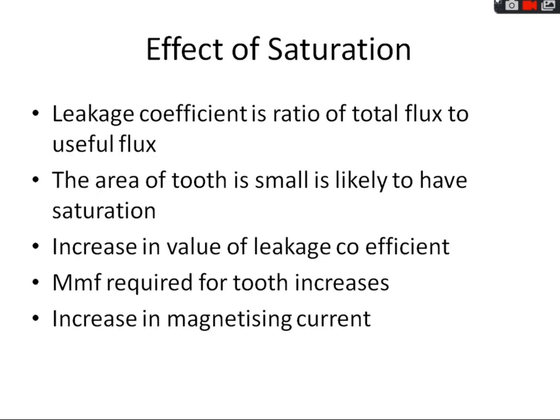Now, this magnetomotive force or the magnetizing current also gets affected by saturation. If the magnetic flux in the induction motor saturates, then definitely there will be an effect on the magnetizing current, because finally it is going to affect the magnetomotive force.